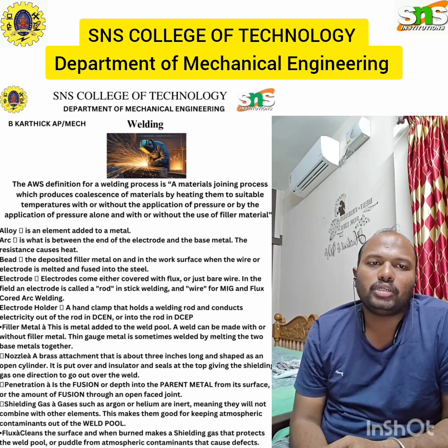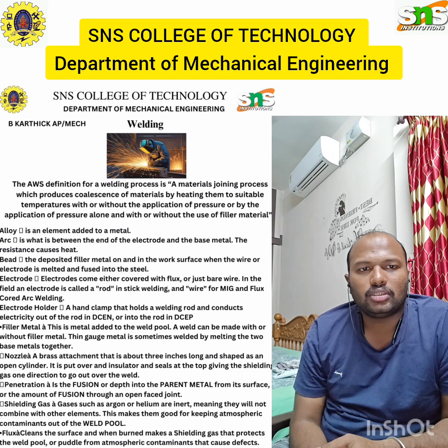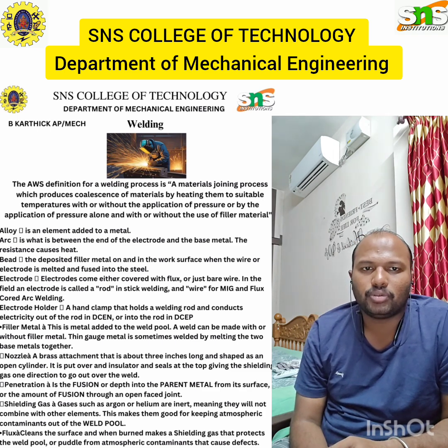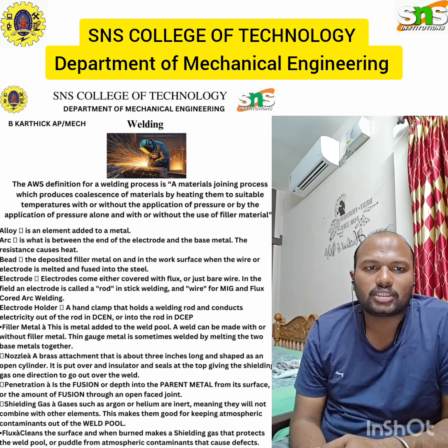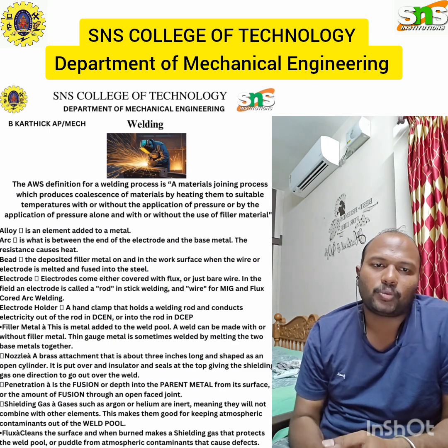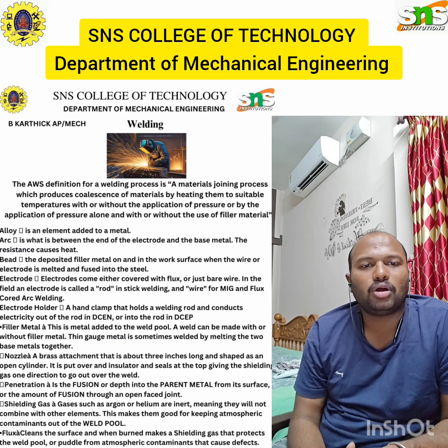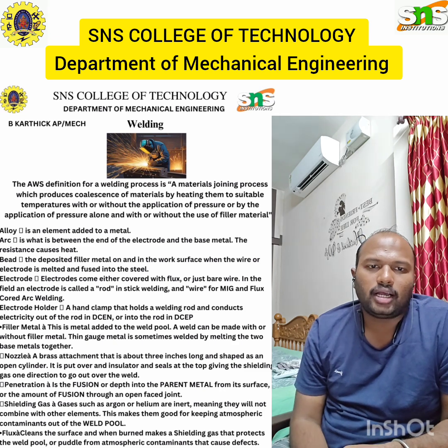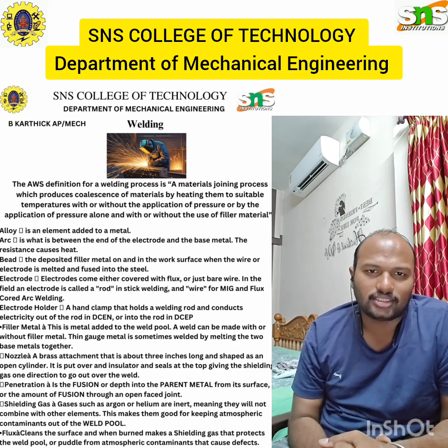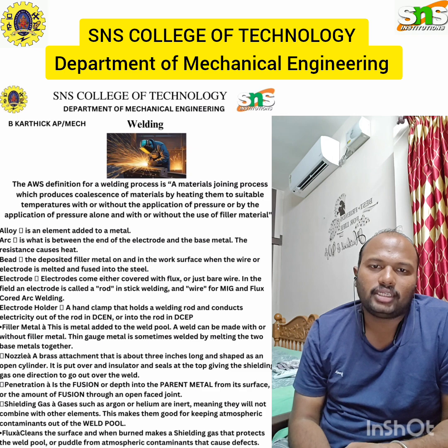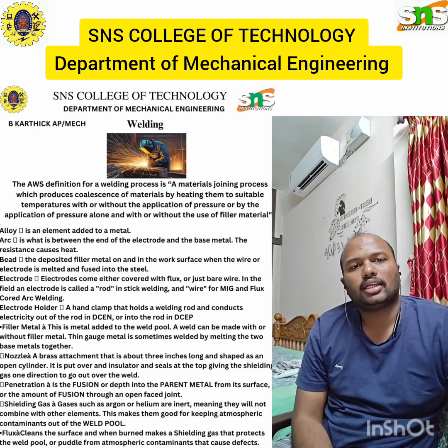The molten pool is sometimes called the weld pool. The control of current and travel speed is most important for this weld pool, and the weld metal deposit is covered by a slag from the electrode. Almost all the electrode metal is transferred to the weld pool. A small amount is wasted, and that is called spatter. After that, the slag is removed and cleaned.